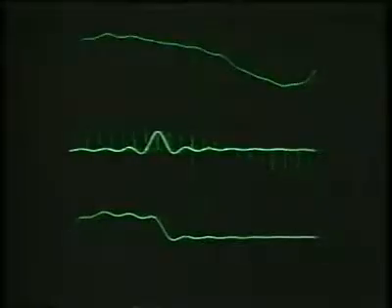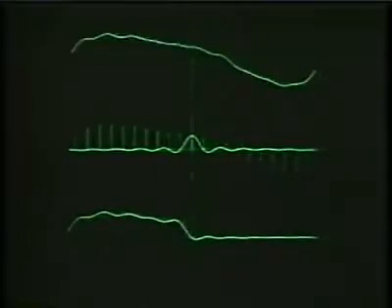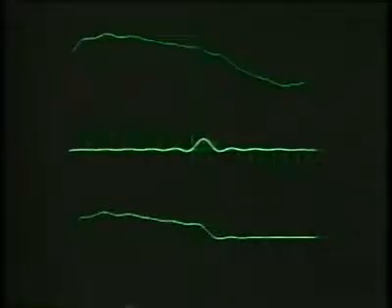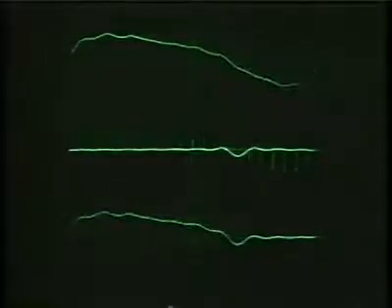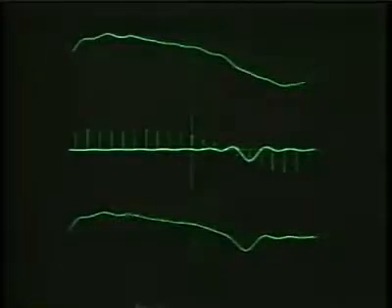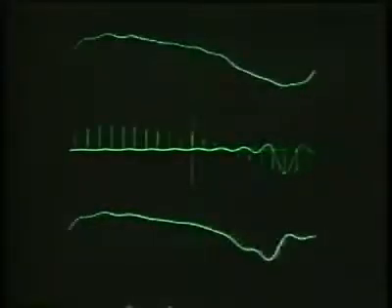And keep in mind the fact that basically what we're doing explicitly here is the convolution of the impulse train with a sin x over x function. And because the set of samples that we started with were samples of an exactly band-limited function, what we are reconstructing exactly is the original continuous time signal that we have on the top trace.